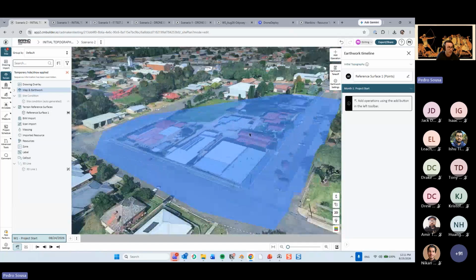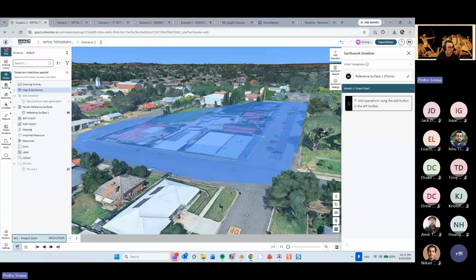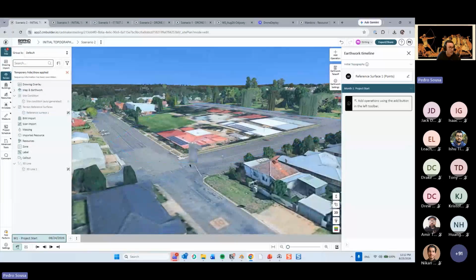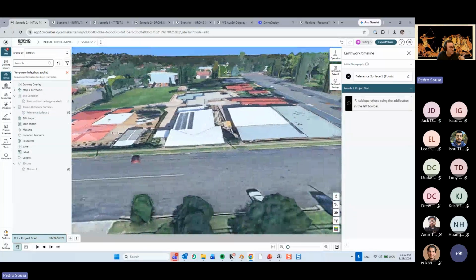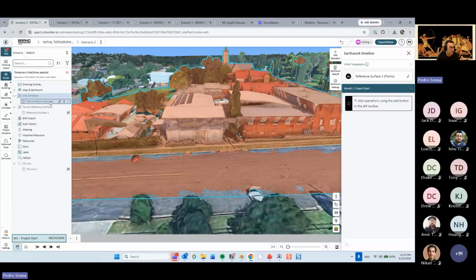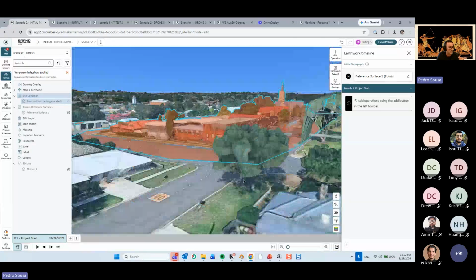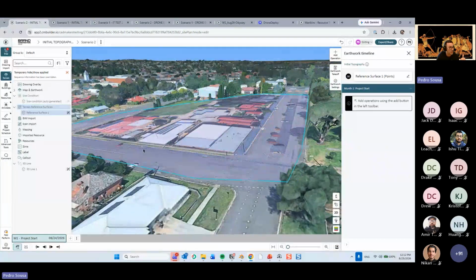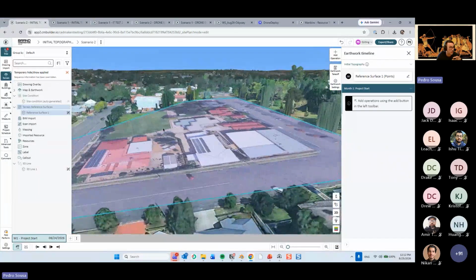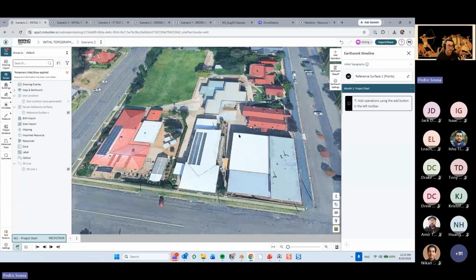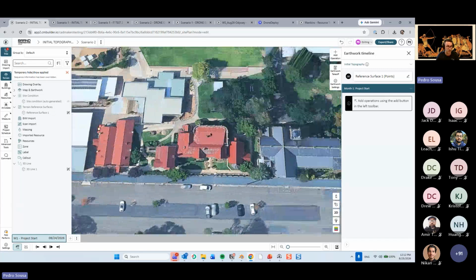And for now, what cmBuilder did was to replace the whole shape of this reference surface with the initial topography. So as you can see, it created a site condition automatically for me. And from this site condition that it created automatically, it took it all and put the shape of the surface instead. So right away, you can see the difference between that distorted site condition topography that we had before and this topography now that is supposed to be the actual topography of my site.